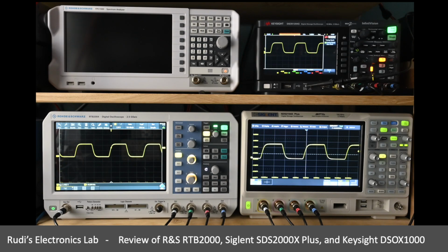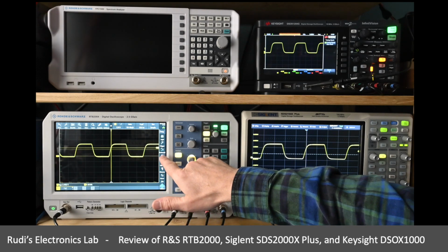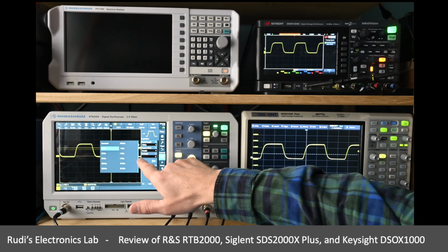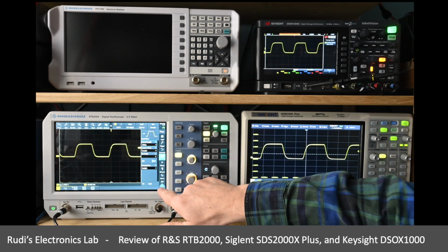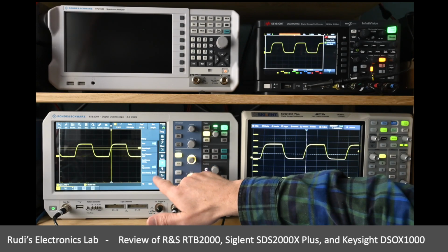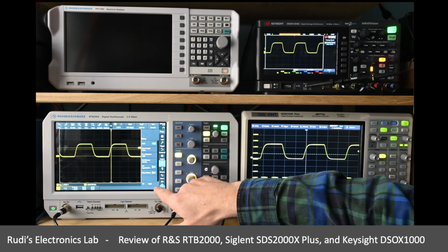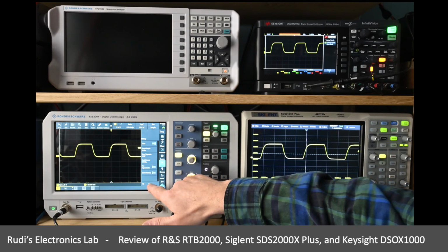I put all the devices to the same time base and comparable vertical settings. It's all 10 microseconds per division. And we also want to choose the optimum setting for each of the devices to be able to see what we're doing. Now that is often related to the acquisition system setting. So here for the Rohde & Schwarz, basically I'll choose the shortest record length. That's probably going to show me the best results here. And in terms of what I've just been talking about, the fast segmentation mode, I'm going to turn that off, so we get the maximum screen updates here.